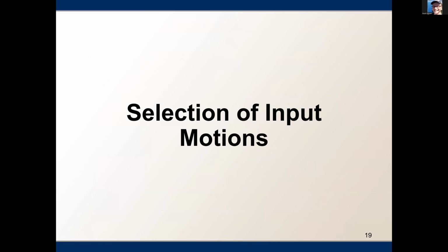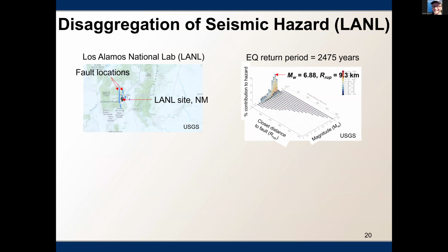So with this, I will move on to the selection of the input motions for performing site response analysis in Palestine. To select the input motions, the first thing I did is the disaggregation of seismic hazard.